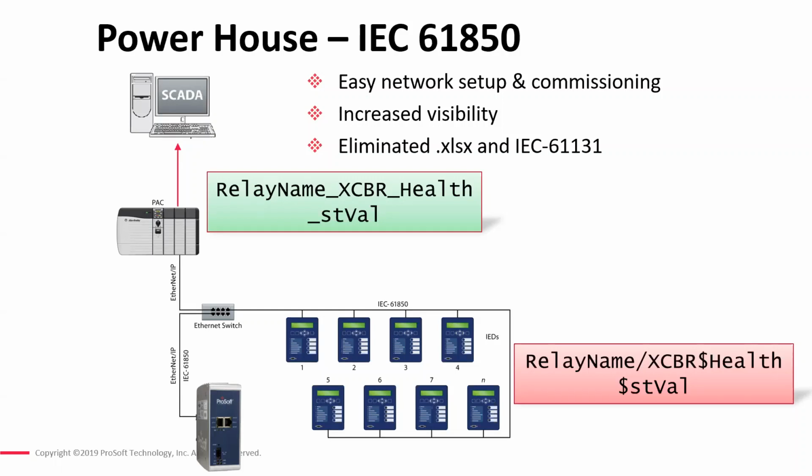When you look at mapping sequence of events over to Ethernet IP or Modbus TCP/IP, there is really no sequence of events data structure outlined in those two protocols. So we can grab SOE data from an IED.